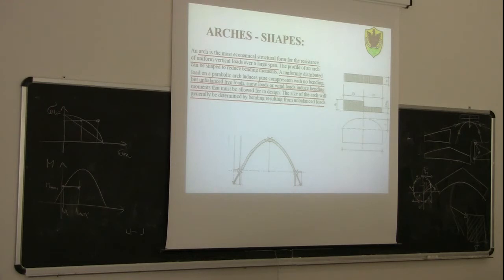Snow, sure. So the snow you have to consider the unbalanced. Usually we don't do this, but if we design an arch, the balance is, by the way, the most important one. And on this note, also you saw recently wind. Okay? Then theoretically also the maintenance. The maintenance is a variable load you should consider also that. But we said the snow usually covers also maintenance, so the snow is more critical than the maintenance.